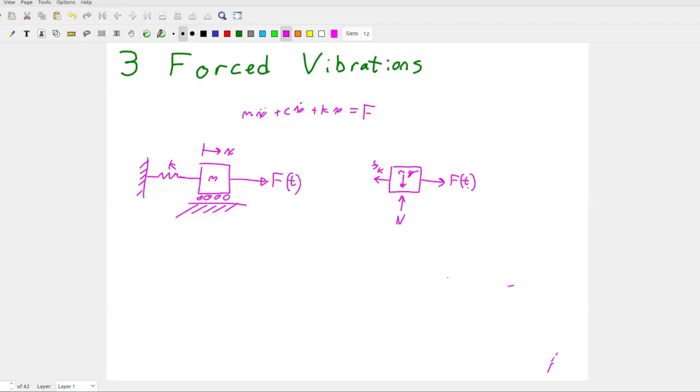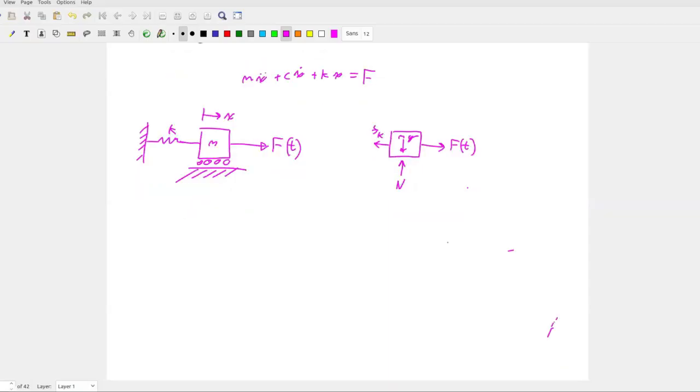So we need to develop a solution for the equation of motion for our ordinary differential equation here. And so we're going to start by just making some assumptions, tossing them into the equation and seeing what lands, right? So first, I want a sinusoidal loading, right? If I just pull to the right, I don't get any vibrations. It's a vibrations class. So I'm just going to say, you know what? F of t, that was fun and all, but let's make that a little bit more defined. I've got F naught, which is an amplitude, cosine of omega t. This is just going to give me a forcing function that looks something like that. I'll make it another color. We'll make it blue.